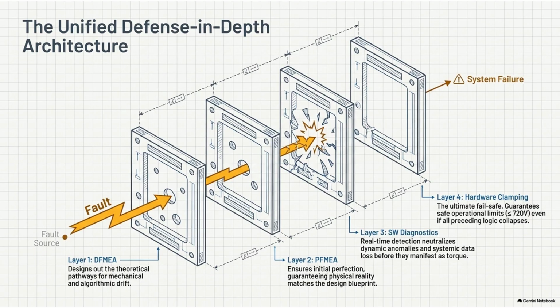Torque ripple, meaning the physical jerk or shudder felt by the driver, has to be so small they barely even notice it, even though the motor just lost its primary sensor while pulling massive current at 12,000 RPM. Precisely. And crucially, if they inject a severe enough fault to trigger the hard clamp, the controller must deploy those stepwise ASC short circuits perfectly, absorbing the massive energy spike to keep the DC bus voltage safely under 720 volts. No blown inverters, no fires, no exceptions.